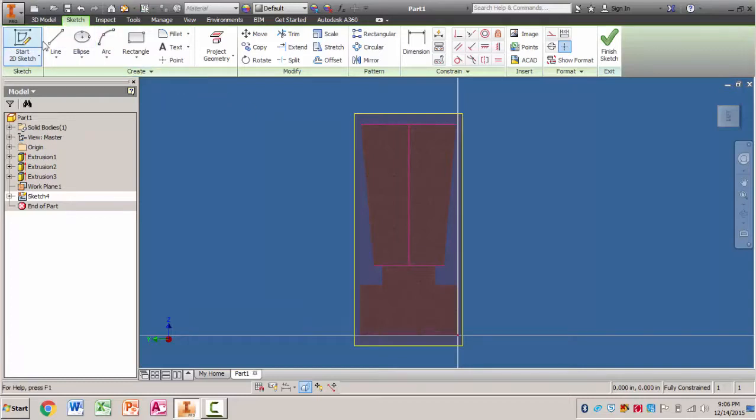I'm going to take my line tool and pick a place that looks about like where they did on the drawing, which is about here, and I'm going to drag straight over and make it 0.6. Then I'm going to hit escape, choose my line tool again, and go from that same point to the left, 0.6. That's going to create a really nice symmetrical arc when I draw it in here.